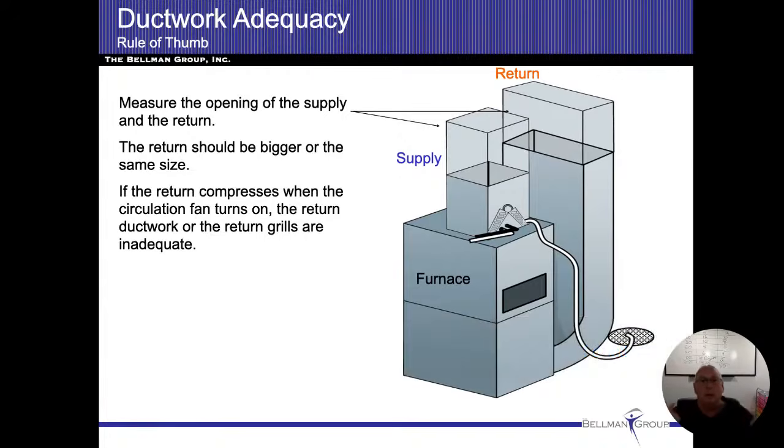the ductwork. So if the ductwork starts collapsing and going up, so I don't know if you've ever heard when the furnace shuts off, all of a sudden you hear this big whomp in the ductwork as all that pressure is released. That's a pretty strong indicator that it's not the right size. Now, it's still hard to justify, tell someone, well, you're going to have to tear all the ductwork out and put bigger ductwork in.